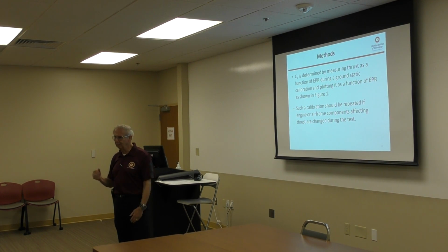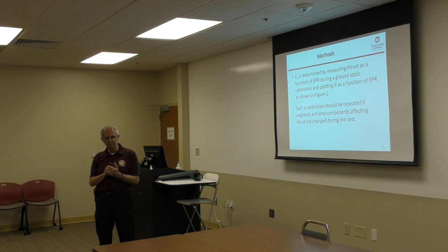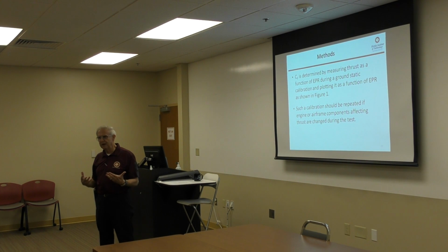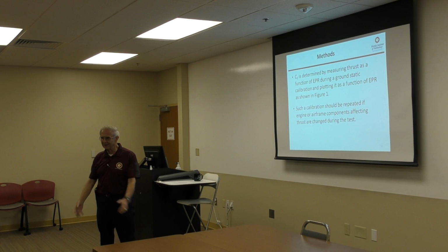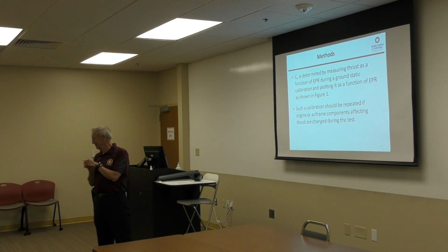Okay, so we were able to run the engine at various power settings. I had a student standing off the side so he didn't get blown away with a pair of binoculars looking at the load cell, okay? And he was writing the numbers down there. I was writing the numbers down in the cockpit, what we would set for various things. And we were able to calibrate it, and amazingly, the data fell right on top of the 40 by 80 tunnel data.